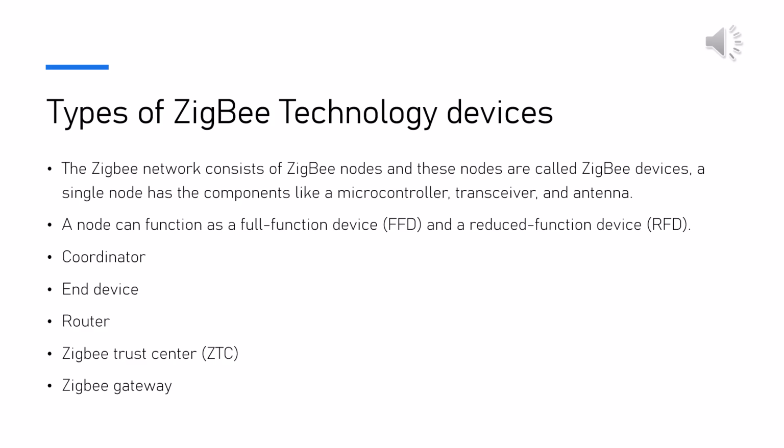The Zigbee architecture consists of the APS, which is the application support sublayer, the Zigbee device object, called ZDO, and the user defined applications. There are two modes of communication in Zigbee, a beacon mode and a non-beacon mode. The beacon mode is used to save power, and the non-beacon mode is for exchanging information via the network. An example is a smoke detector.